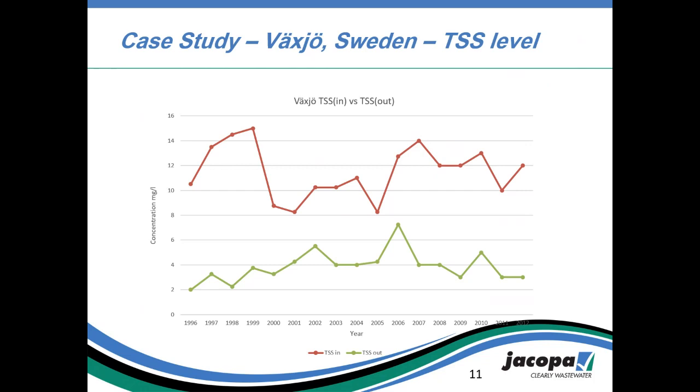So this is from the final settlement tanks, roughly 8 to 15 milligrams per litre coming onto the filters. And if you remember, the consent was 8 we're after, and you can see we're consistently meeting that year in, year out for the time scale on there, which is nearly 20 years. So you can see it's achieving its TSS objective.